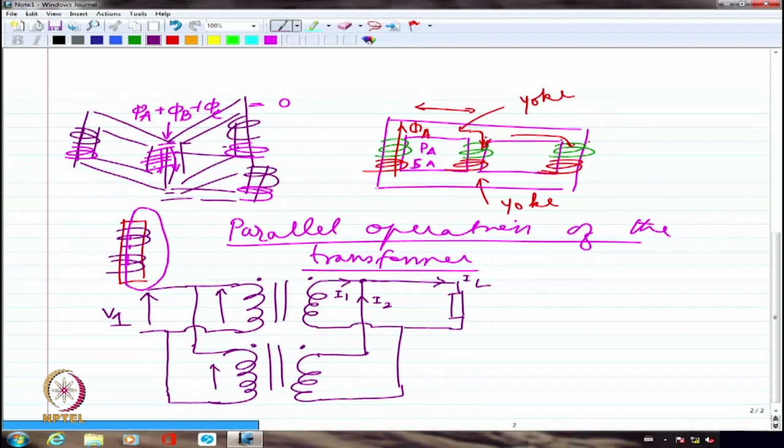Let's say when we started with the IIT building, there was only the textile technology department and a couple of administrative blocks. The total load would have been of the order of maybe 20, 30 kVA, nothing more than that. So maybe, even thinking about expansion, a 100 kVA transformer was installed. And now everything has proliferated in exponential fashion, so we really do not have sufficient transformer capacity.